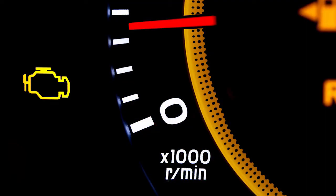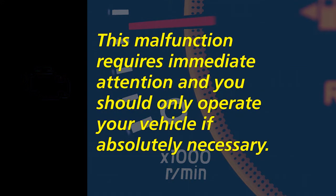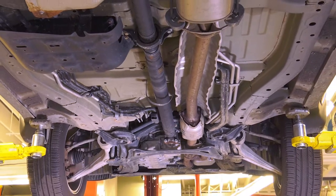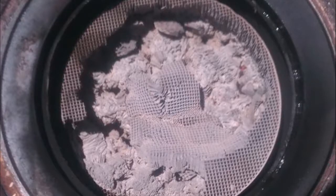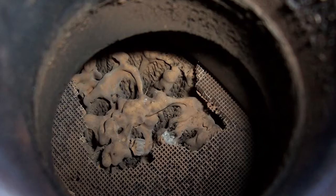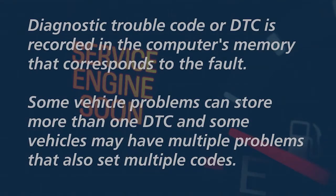If the computer detects the possibility of a serious malfunction, the light is commanded to flash on and off while the engine operates. This malfunction requires immediate attention, and you should operate your vehicle only to get to a place of safety. System faults that cause the check engine light to flash could result in serious damage to the catalytic converter or engine.